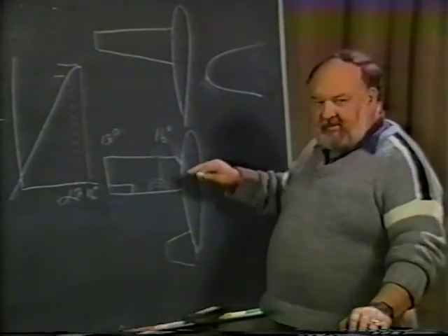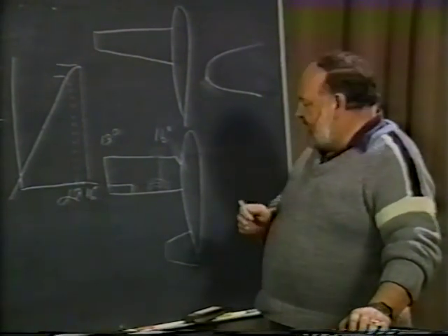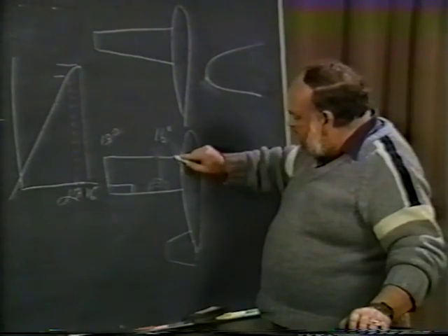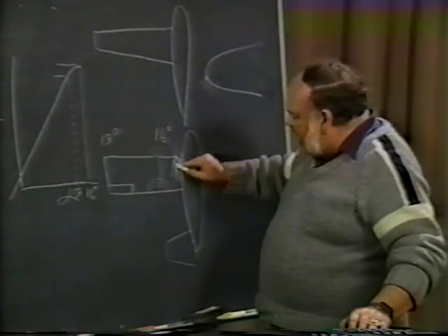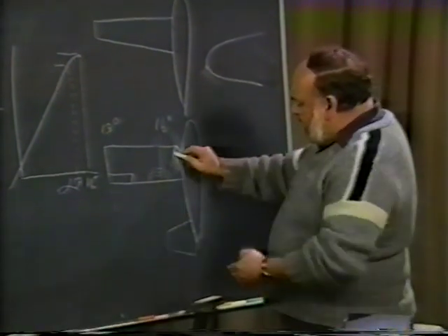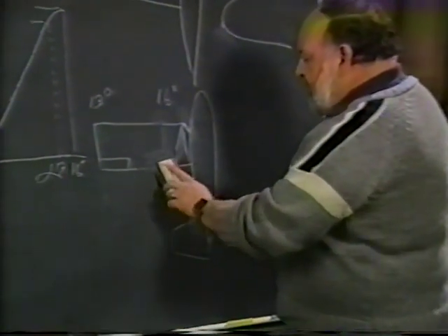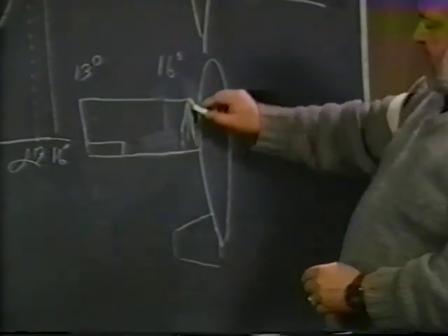His windshield now is at a much lower slope angle, less drag on that, good visibility with it. But one of the key features is that this sharp edge here causes a flow vortex to build up as the air comes around the leading edge and it gets the sweepback, it rolls around, and this region in here is the region that will tend to stall. So he ends up with a real nice stall pattern, forcing it right inboard here.